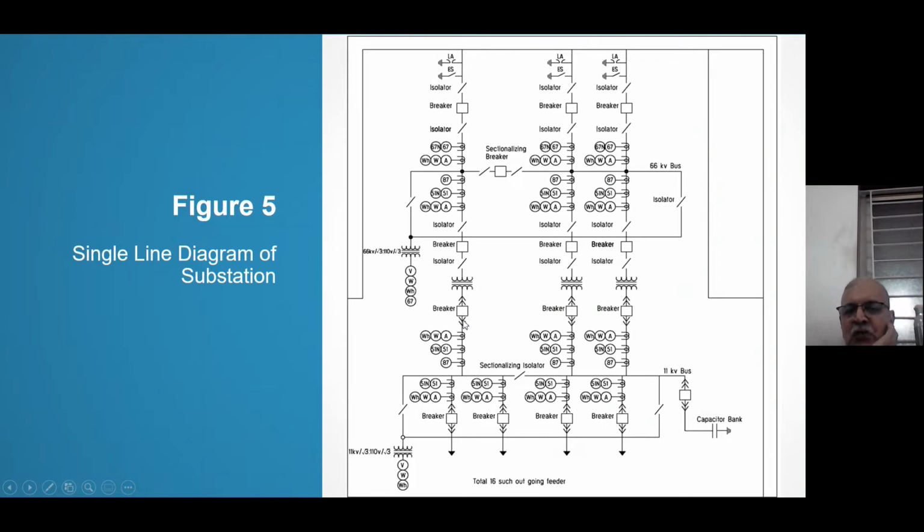So here if you see, there are two lines, I mean these two arrows are shown. That means this breaker is an incomer breaker, an indoor breaker. This is not exposed to rain or anything. This is in the building, right? These relays are also in the building. Even these relays, all relays are in the building, but CTs are outdoor. But CTs on this side, the 11 kV side, are indoor. On the 11 kV side, everything is indoor.